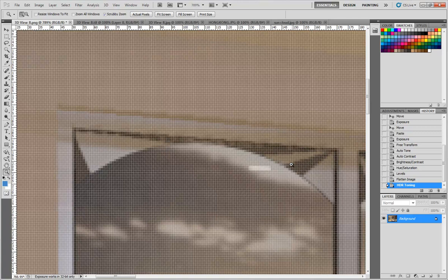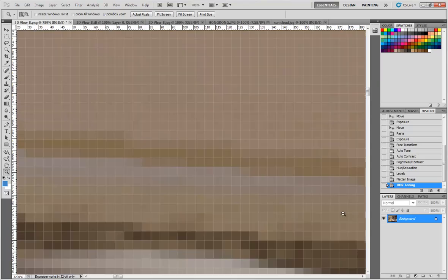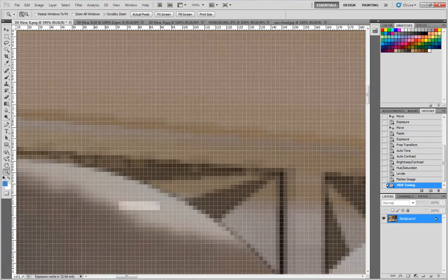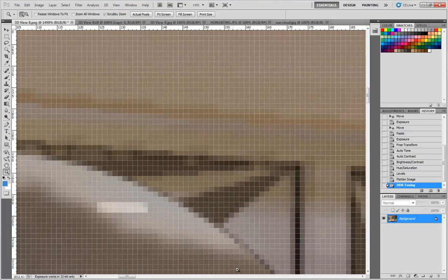It's a rendering artifact, and it could be caused by problems in the geometry. So I might have modelled that badly, and there could be glass overlapping the framing or something, or it could be some other rendering issue. Now, I could go back into Revit and fix it, hopefully, and re-render it, but if I'm in a hurry, or if I just can't work out what's causing it, another way would be to just correct it in Photoshop.